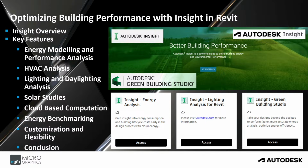Lighting and daylighting analysis. Insight provides simulations that allow designers to evaluate lighting levels and daylighting strategies. The tool shows how natural light penetrates the building based on window placement, size, shading devices, and reflectivity of interior space surfaces. With daylighting analysis, architects can adjust the design to maximize natural light, which not only enhances occupant well-being, but also reduces the need for artificial lighting. Designers can also explore how shading elements impact daylight levels, balancing thermal comfort with lighting efficiency.